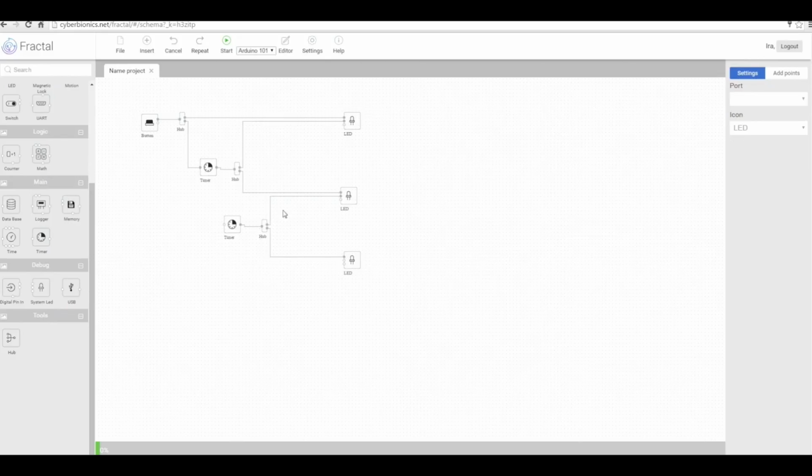Thereby, the timer should be activated at the same time with switching the yellow LED on. For that, we add one more point to the hub and send the command on the timer. Pay attention that after the first timer, the control signal at the same time gives the command to the red LED for switching off, to the yellow one for switching on, and to the next timer for activation.